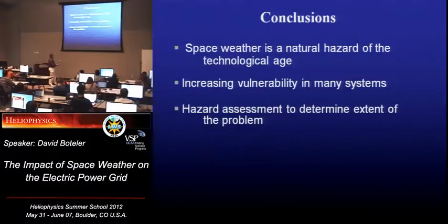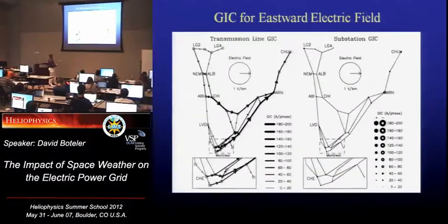And if I can just go back. In fact, this was something that I still think there's confusion about with the Hydro-Quebec system, because their main lines are north-south, and that's where the power flow is. The AC power flow is coming down from generation up here, down here. So they tend to think of that as mainly a north-south connected system, and almost don't take so much notice of these interconnecting lines in the middle.